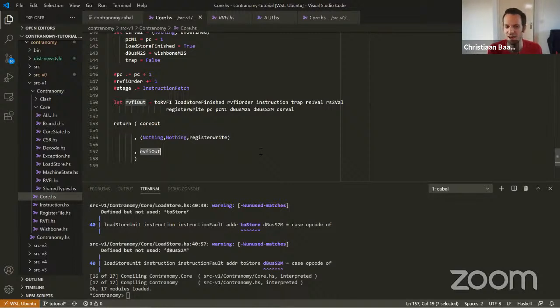You also need to tell it for how many cycles it needs to run to get a proper trace. That's the problem with bounded model checking. But for our configuration, we've given it enough cycles to make sure that our traces are long enough to verify formally.